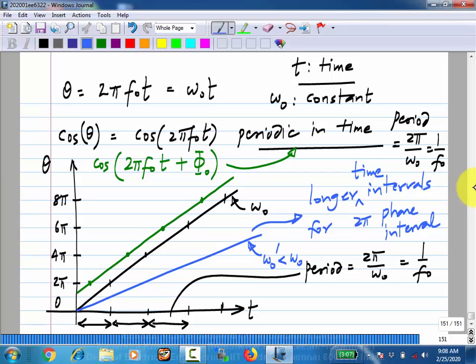And also sometimes you have to deal with signals of different frequencies, and one way to think about them is you have the phase that is incrementing at different rates. Okay. So this understanding of this phase is very important for understanding of clock and data recovery circuits and phase lock loops and so on. Okay. Where essentially the phase of the signal is important.